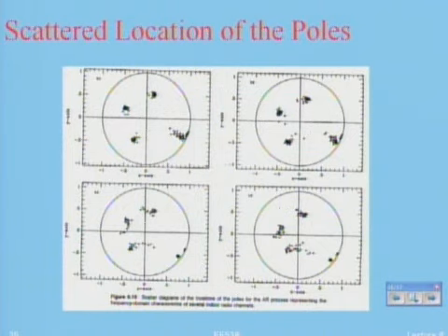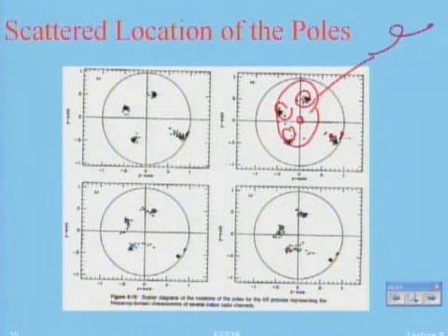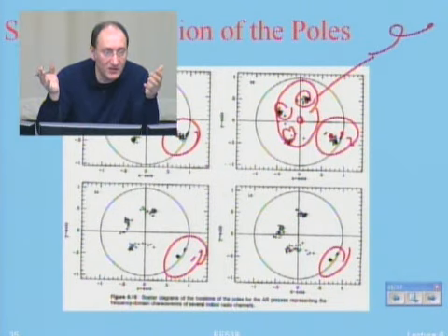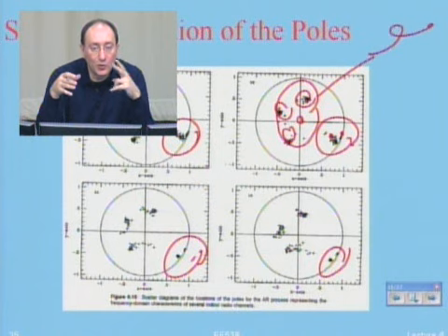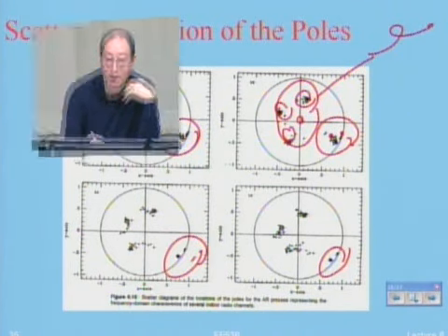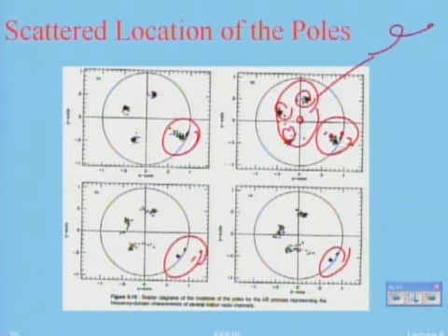I think these are the details of that. These are fitting of Steve's model to poles. He has like, these are 2 poles close to the unit circle, 3 poles in the center, which are not important. I can neglect those and keep only these 2. Okay, these are results of measurements. So he takes a bunch of frequency domain models, and he determines 5 locations of poles for the filter. And these are the 5 locations of the poles for different measurements. 2 of these poles are dominant all the time. The rest are redundant.